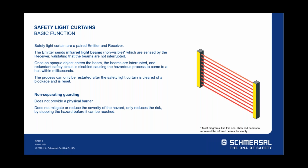We just have a quick note here. It's the non-separating guarding, the easiest way to understand separating and non-separating, the two types of guarding. Separating, there's something there to separate the operator from the hazard. There's a gate, there's a hood, there's a fence, there's something separating. And non-separating, as you can see here, if a projectile flew out of a machine, those beams are not going to stop it. So it's non-separating, which does not mitigate or reduce the severity of the hazard that's in behind it. It only reduces the risk by stopping the hazard before it can be reached. So that's our main goal with these.